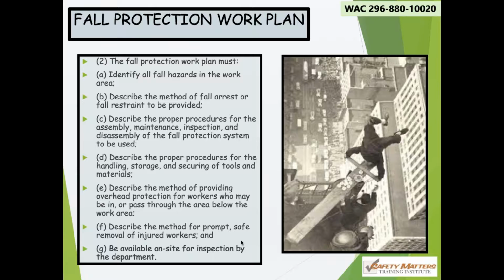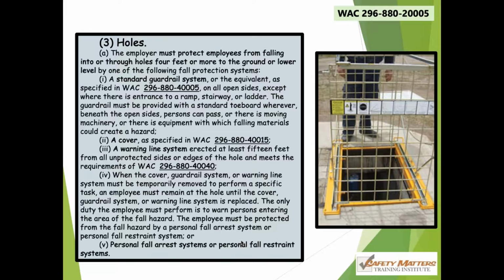You do not kill these things until you walk away from that job, until you're completely finished with that job. So I'm going to speed up here a little bit. Holes, we need to cover holes, right? Remember, a hole is anything that an employee could fall through, into, or through anytime we're 4 feet or more above the ground. The 200 codes are the 4-foot rule.